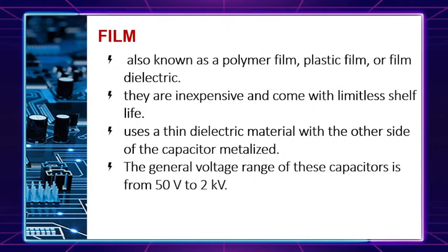The next component for capacitor is the film. Other terms for this are polymer film, plastic film, or film dielectric. So you can easily guess that the dielectric for this component is the film. The good thing about this component is that they are inexpensive and they come with a limitless shelf life. It uses a thin dielectric material with the other side of the capacitor metallized. The voltage range of this component is from 50 volts to 2 kilovolts.